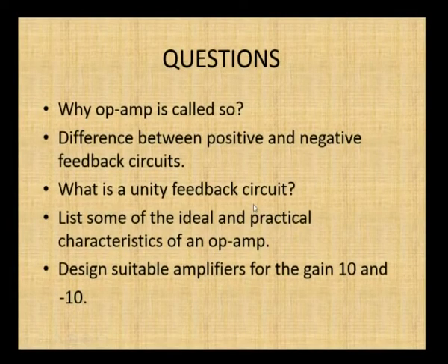What is the importance of this voltage follower circuit? It can act as a buffer, because it transfers the input voltage to its output terminal without any loss, and it also has high input impedance. It is not going to provide a loading problem for its preceding stage because it has a high input impedance. So this is the main point in the voltage follower circuit. It can be used as a buffer.